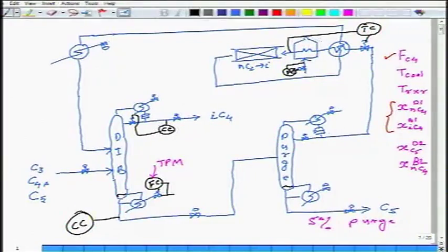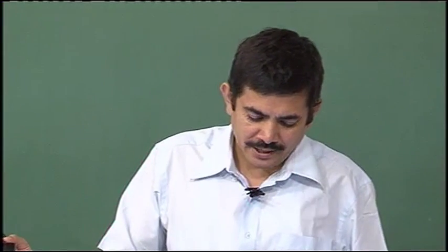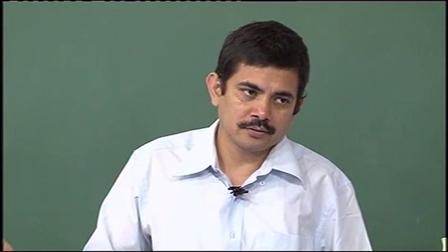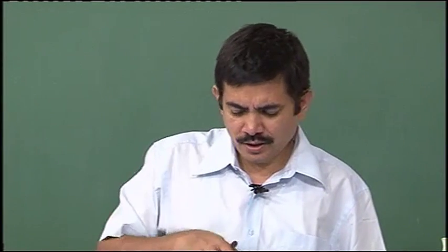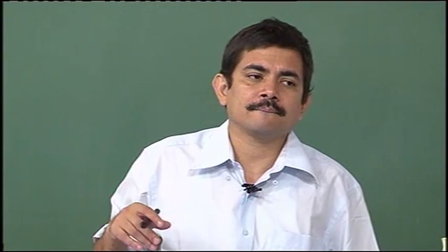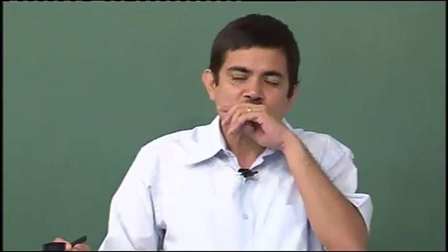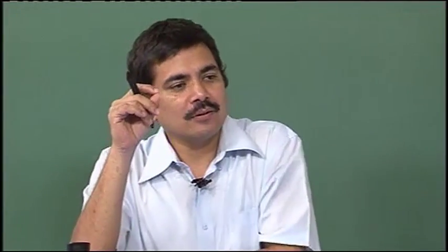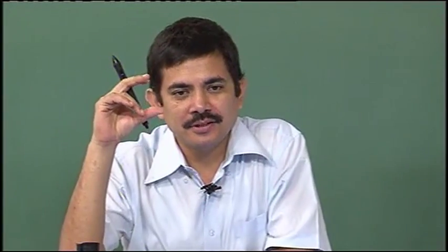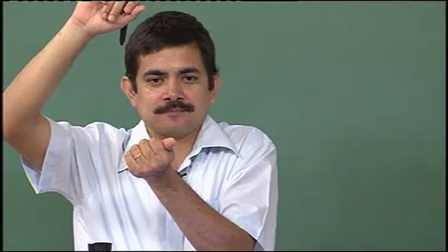What about the lag associated with using the composition controller? Because usually the time is 6 to 8 hours. So yeah, there is a lag associated, so it's not going to be tight. But it really doesn't matter because what's going down is okay. This goes into distillation. So if you can't use a temperature, what you generally use is a delta T, the difference between two tray temperatures.